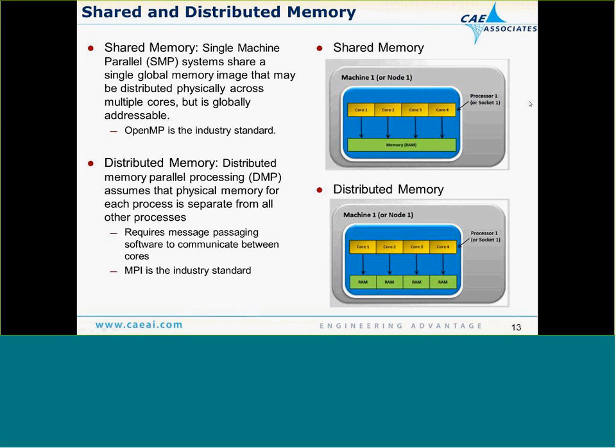So let's jump right into the discussion about shared versus distributed memory. In my experience in tech support calls today, I get a lot of questions about should I be utilizing shared memory or distributed memory. In essence, the trend is ANSYS is continuing to develop most of their solvers, and the preference is to use distributed memory whenever possible. Now, there are certain sets of runs, certain solvers, certain arrangements where shared memory configuration will still run a little better than the distributed memory, but in general, in most cases, distributed memory is preferred.